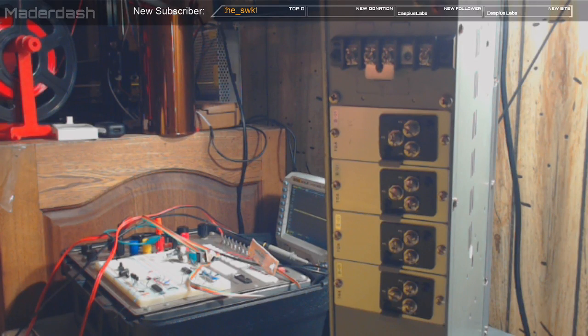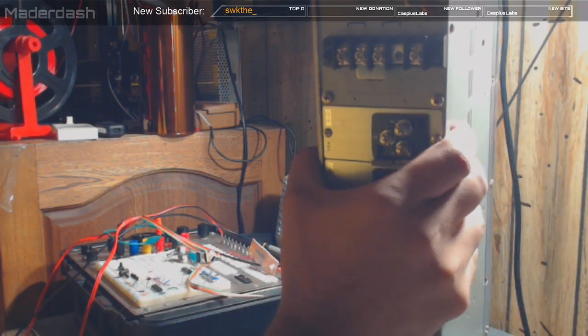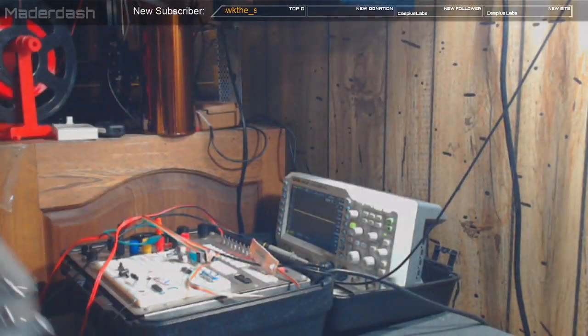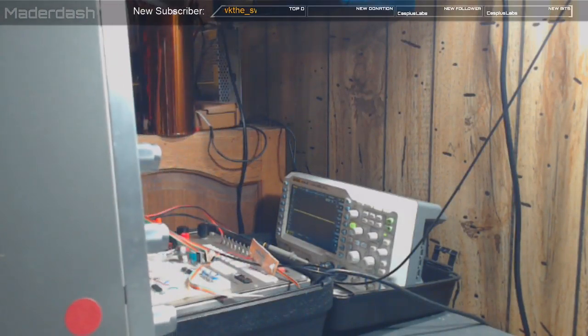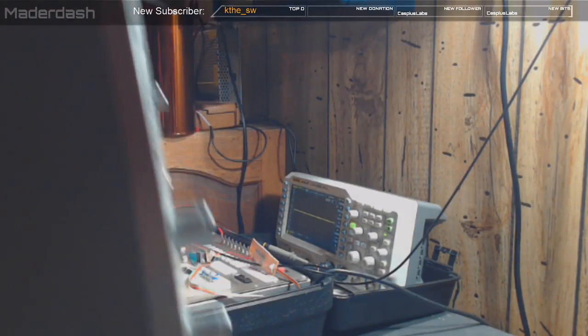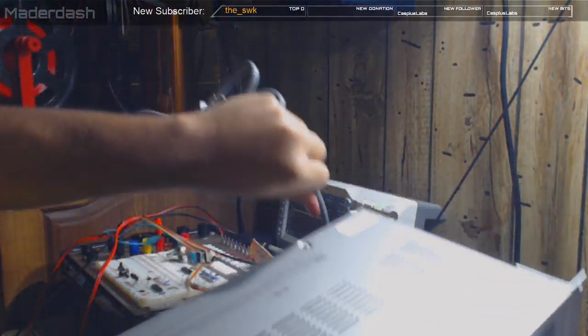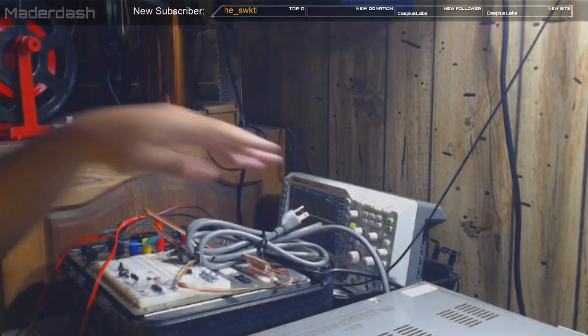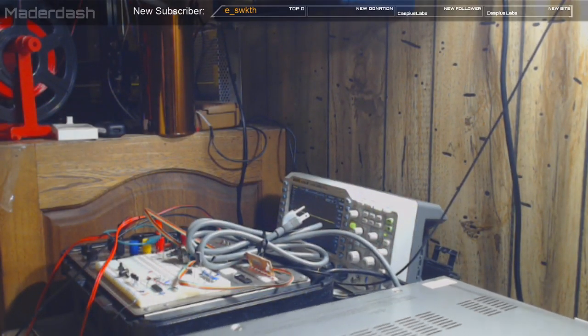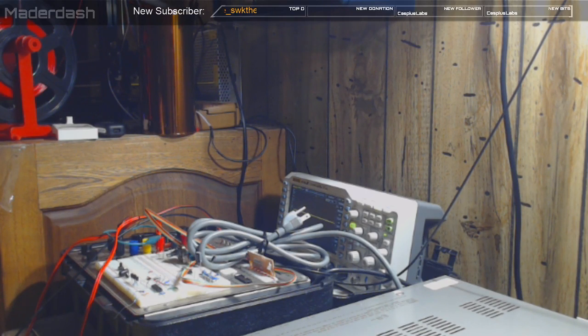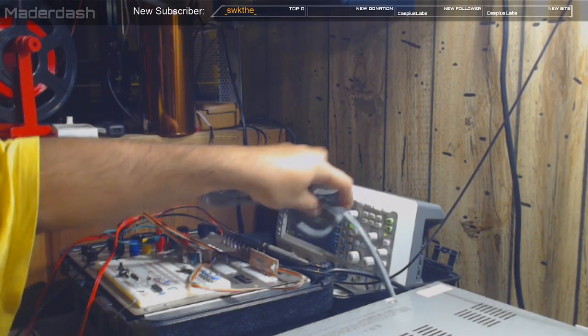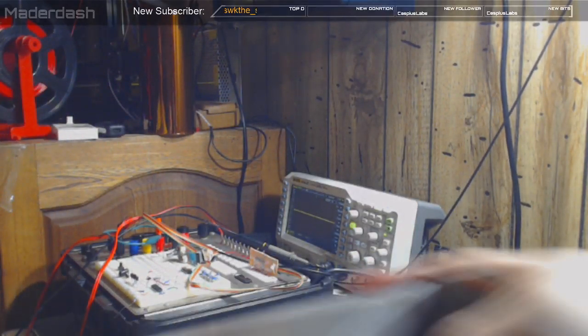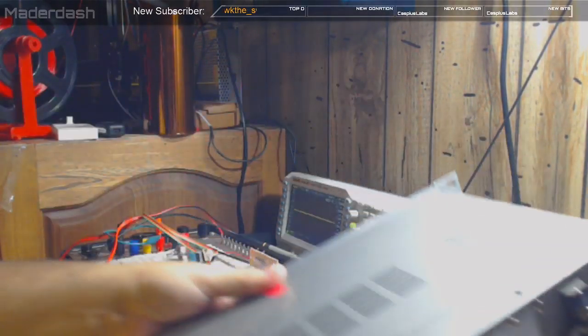So yeah, that's the malfunction. So I guess we could start taking it apart. I don't know how far we'll get on it. It has a bunch of screws. It's very, very heavy. I'm going to say it probably weighs about 25 pounds, for such a little box. I guess the very first thing we could do is just check a fuse. It has an external fuse, so that'd be the very first thing we could check.